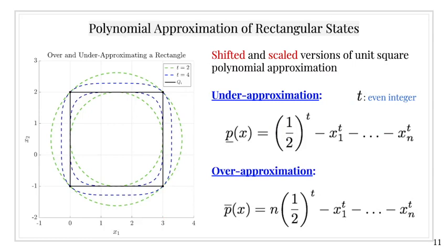It is common to construct domain partitions where all states are rectangular. Therefore, we need to construct type polynomials which are positive for all states inside a rectangle Qi and for all states outside the rectangle to represent its complement so as to encode the set constraints from the previous slides.